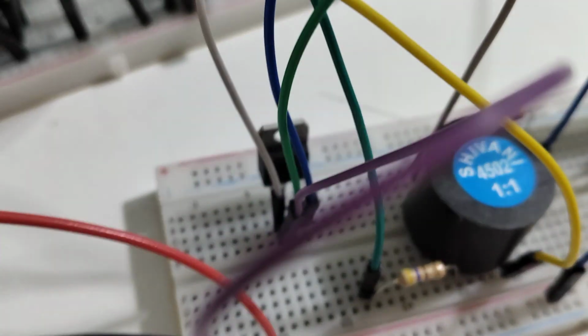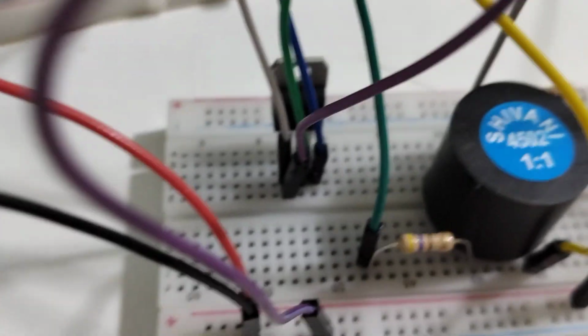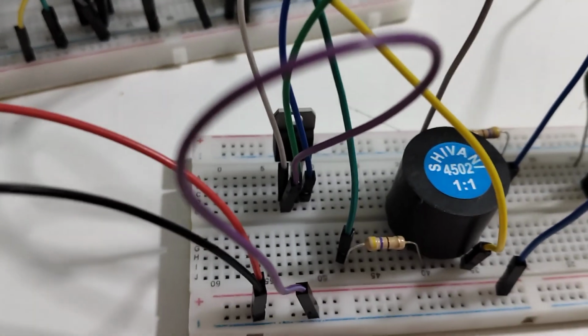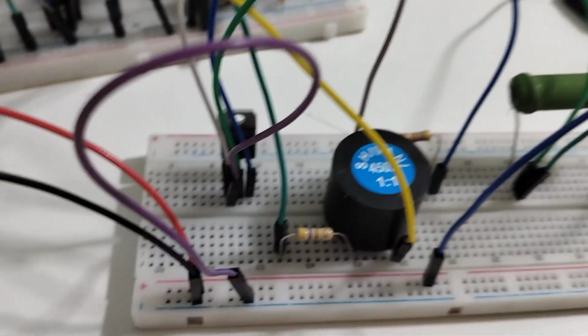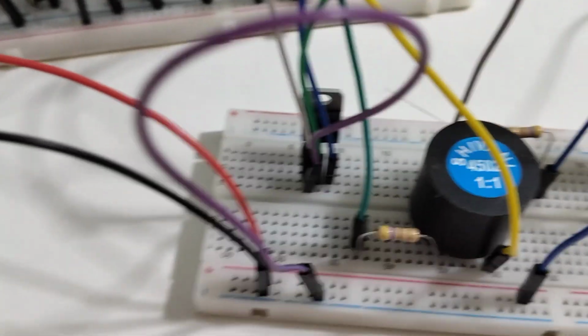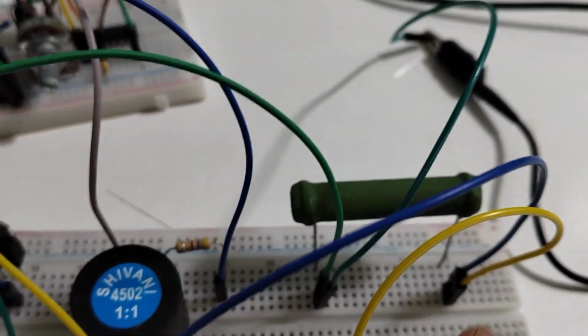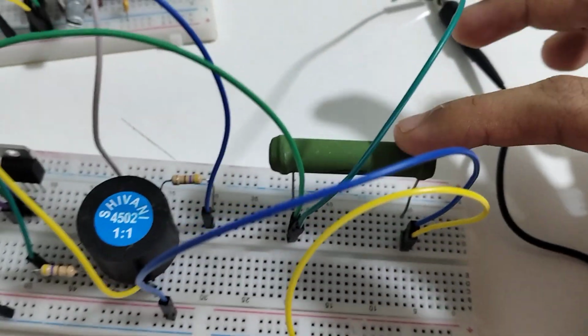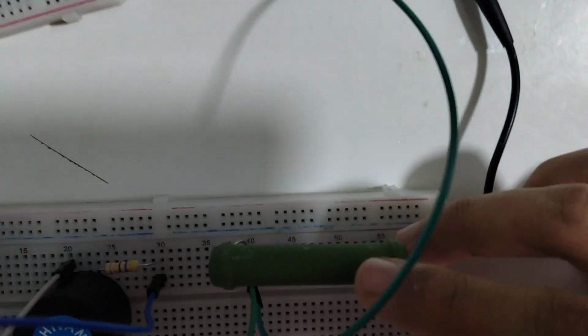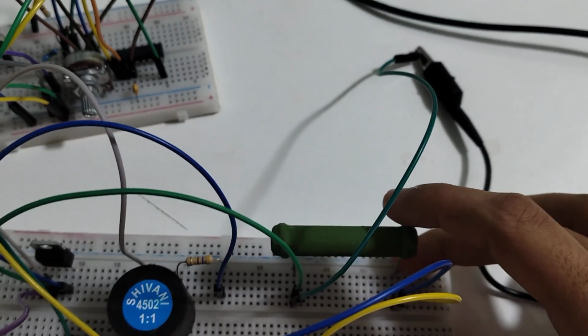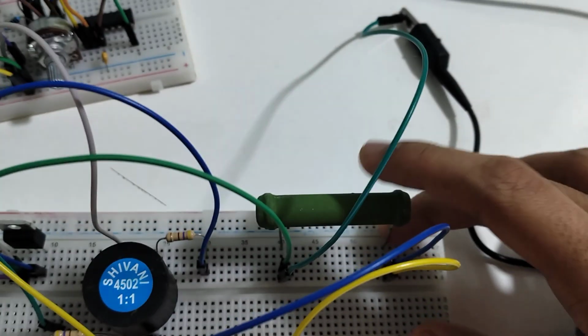I'm using the TYN1225, which is a 1200 volt 25 amp rated thyristor. So you can clearly see the ratings. You can just calculate the power, how high power it is, and I'm definitely not pushing that power, but nevertheless, it's a high power rated thyristor. And this is the 100 ohm load, as I said. It's going to be dissipating at least 1 or 2 watts, I believe, if you calculate.